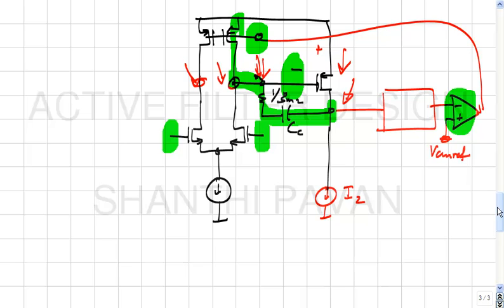But there is also the input to the filter, right. If now I kind of wiggle that around, hopefully it will get out of this state, but that's now taking a risk, a big risk, isn't it. So is it a stable state? This is clearly a stable situation as long as the inputs to the... Yeah. So now you are hoping that not only is the input common mode... you must make sure that the input common mode is high enough such that this turns on. If it does not, it does not help.